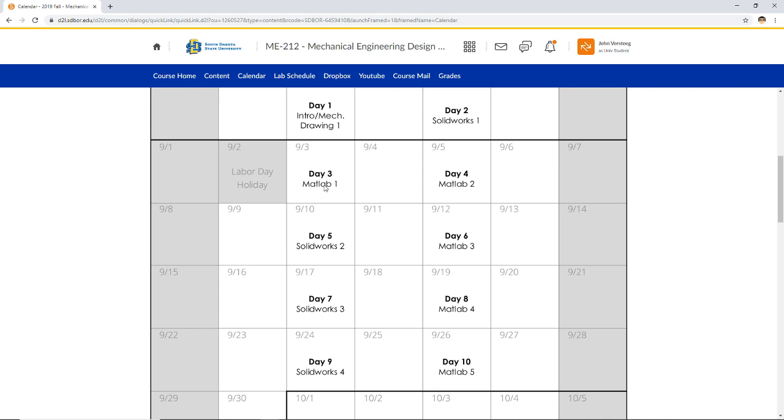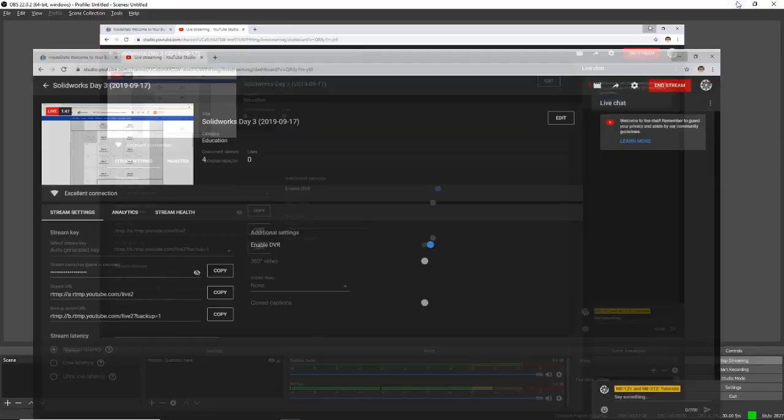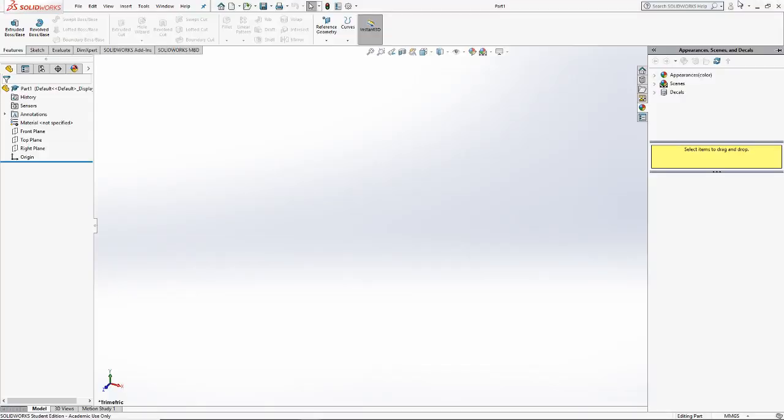What I want to do today, here on our third actual day of SolidWorks, is to talk about revolved extrusions. So under the Features tab, next to Extruded Base, you have Revolved Base. And once you have material in SolidWorks, you also have the Revolved Cut. The Revolved Base and the Revolved Cut both reference rotational symmetry.